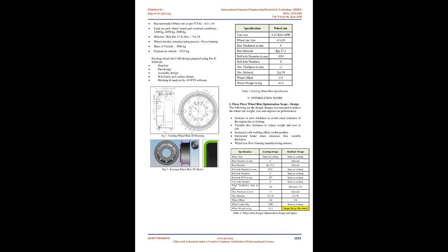3. Methodology. The methodology involves technology for performing the designing and analyzing of the object. Design and modeling of 3-piece wheel rim. Dimension specification. Analysis by ANSYS. Analysis to perform at various load conditions on existing and modified rim design. Analysis of wheel rim under boundary conditions to obtain deformation and von Mises stresses of the model. Obtain the optimized wheel rim and compare with the existing model.